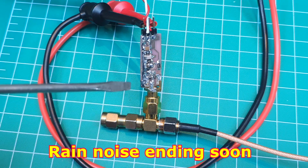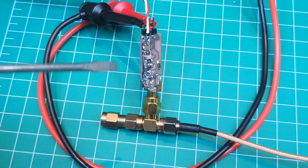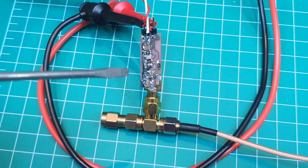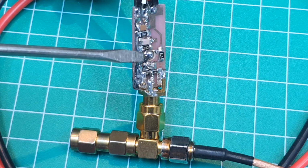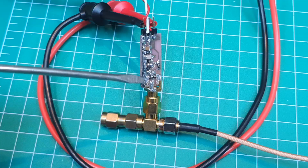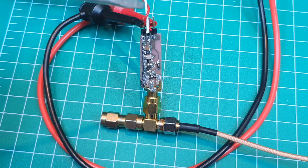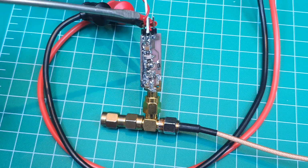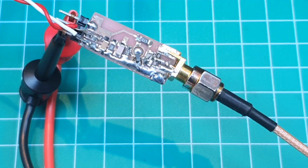This is something that I want to explore in next videos, and I have been trying a lot to generate very fast pulses using very few parts. So here we have one of my prototypes. Here in the middle we have a very small transistor that is avalanching, and it generates a very fast pulse. The circuit is supplied with 32 volts and a trigger pulse coming from a signal generator. By connecting it directly to the oscilloscope, we can see the shape of the pulse.